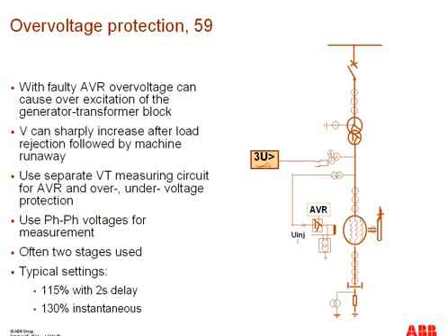Another type of protection is the over voltage protection. Over voltage protection is provided with inverse or definite time characteristics. Over voltage conditions will occur in the power system during abnormal conditions, such as sudden loss of power or tap changer regulating failures, for example, or open line ends for long lines, for example. So several conditions.